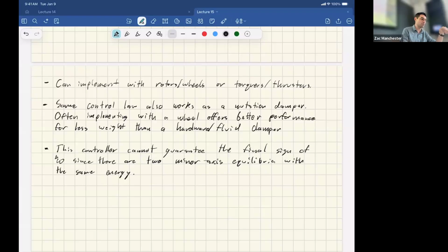If you're underdetermined, and instead of the 2 norm least squares thing, you minimize the 1 norm, remember I said before that will try to zero out as many of the u's as possible. In signal processing, that corresponds to a sparse solution vector, and that's called compressed sensing. It's really cool.